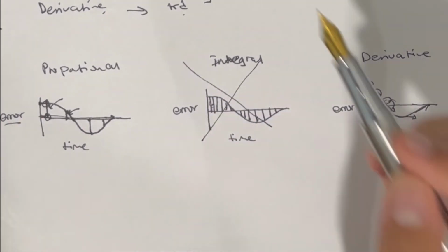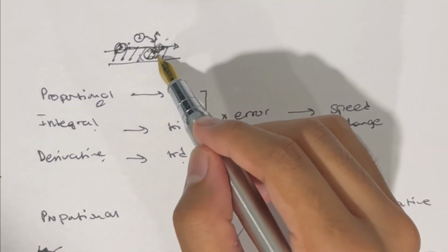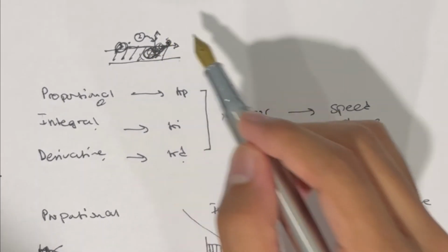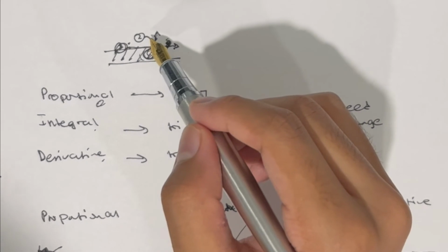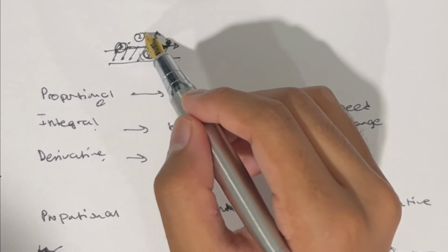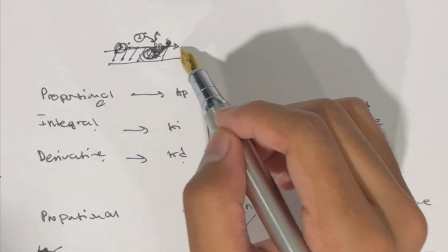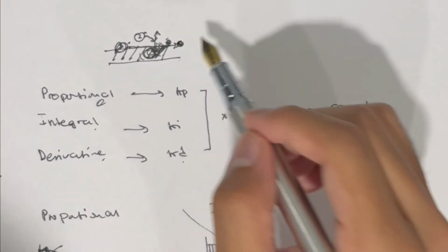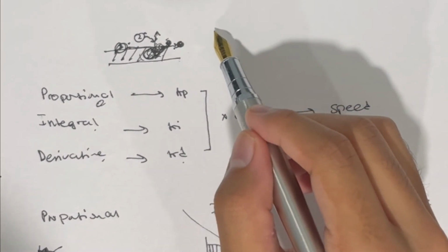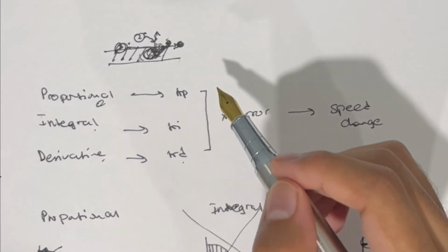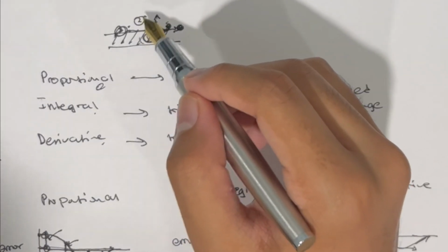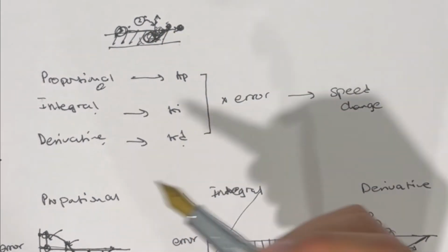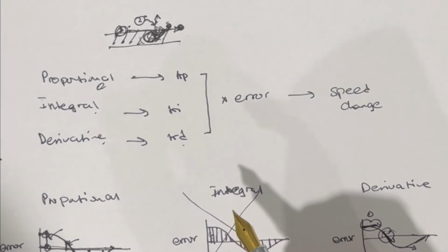And this is because the robot generally does not have a hard time moving away from the black. Once it's on the black part of this line, it tends to move out. But at the same time, it does have a lot of trouble coming from the white back to the center. And this is because in competitive environments, the target value that you're trying to aim for is usually greater than 50. And when the target is greater than 50, that means that you're going to have smaller errors whenever you're on white and larger errors when you're on black. And that means the adjustment for getting off of black is always going to be greater.